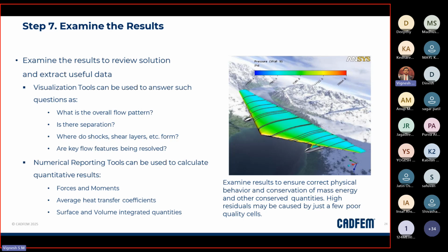All this, maybe you can also look at the lift distribution on the wing for your requirement. You can understand it, and accordingly you can change the wing designs. You can change it, maybe the wings have aerodynamic twist or geometric twist. According to the lift distribution, you can change the twist on the wing to make sure you have an adequate lift distribution. Also they look for an elliptical lift distribution on a wing. So in that, the lift distribution shall make sure you are having an adequate elliptical lift distribution on the wing or not.